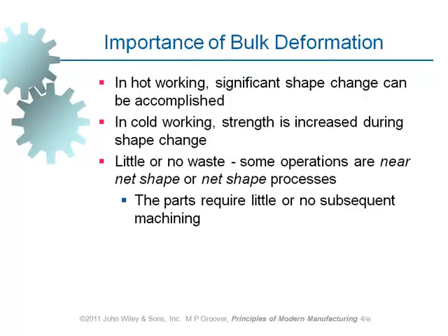If this happens at a temperature below recrystallization temperature, then what happens? Material fails once it's been subjected to a stress which is above its yield strength or UTS indeed, ultimate tensile strength. It eventually fails. But if the same process is performed at a temperature which is above recrystallization temperature, we can still continue the task as long as it is still above that given temperature without failure. So that's why recrystallization temperature is important.